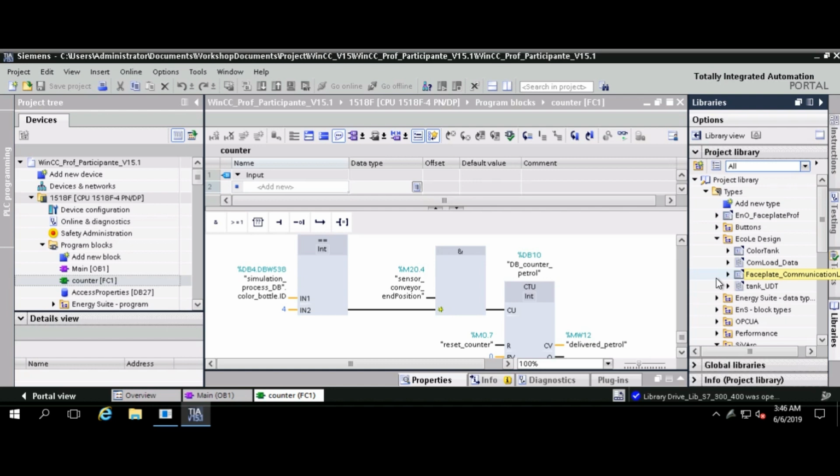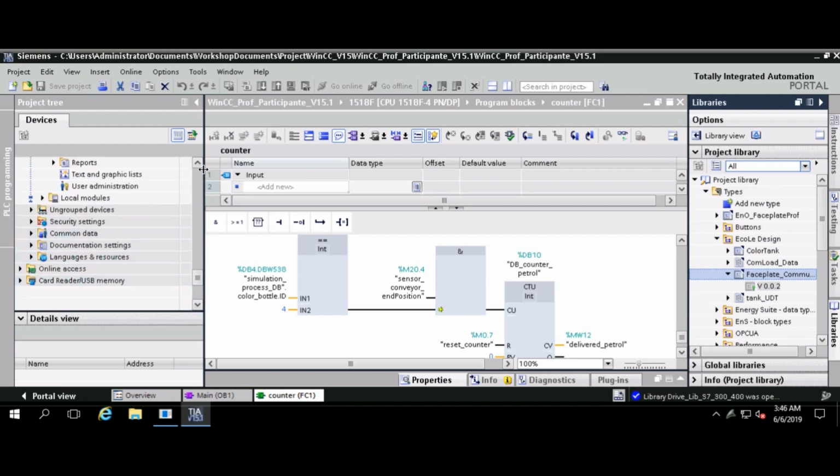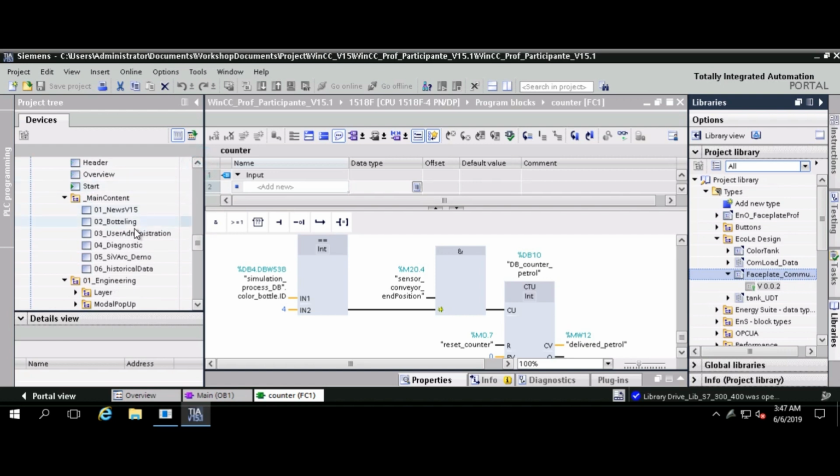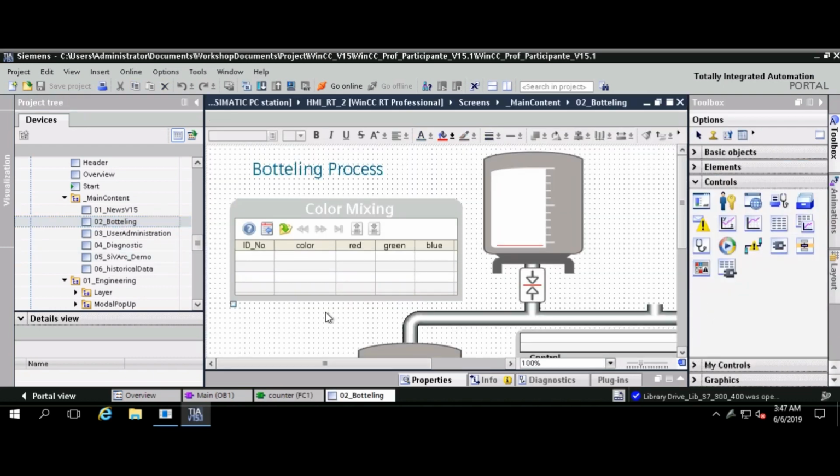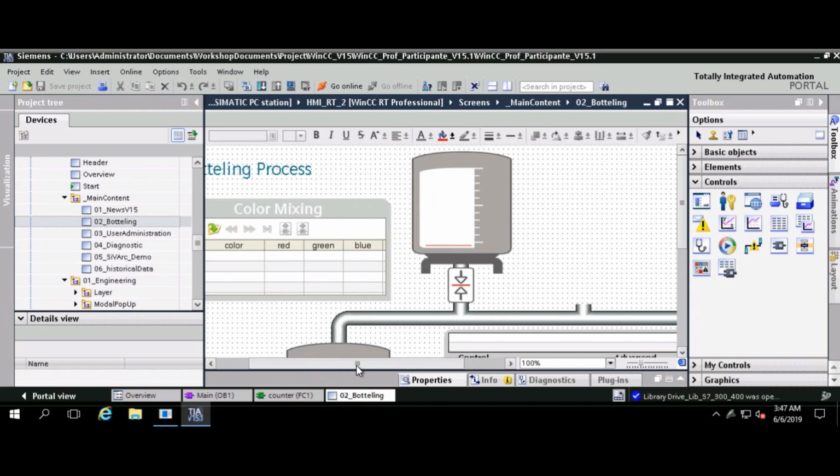Then I change the screen to my library management in TIA Portal. In order to edit a type now, I do a right click on my version of the type and say edit type. Of course, if I do that from my TIA Portal right away, I will jump into this view right away. What I can see here is that a new version got created, which tells me the status is in work. And my old version still exists because I have the option to discard the changes and delete the version, and it goes back to the old version before.